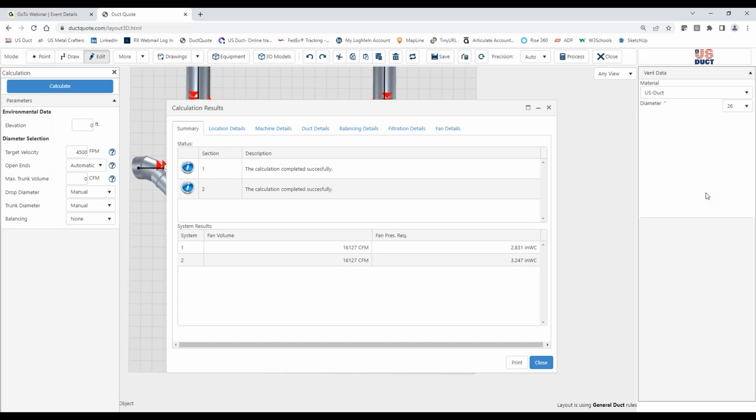And another good idea is think about moving the air always quote unquote forward, meaning towards the fan or collector. Try not to make it go backwards because that means the fan has to pull it away from itself essentially. Now, elbows, its radius, longer radius, lower fan pressure, but uses up more space.